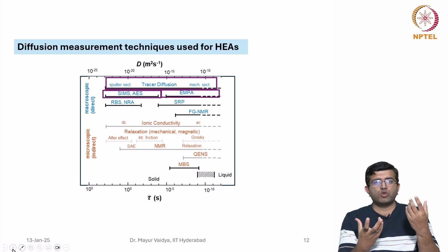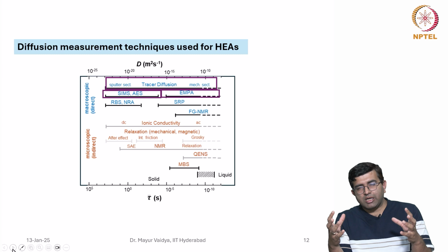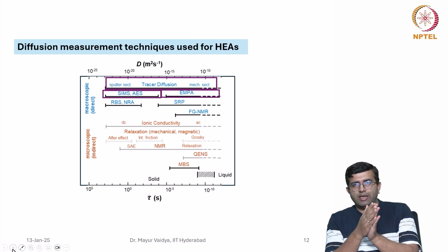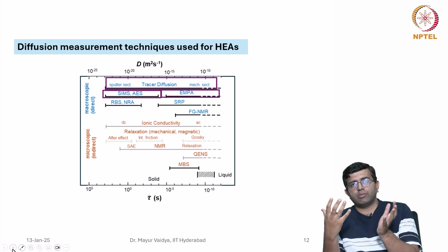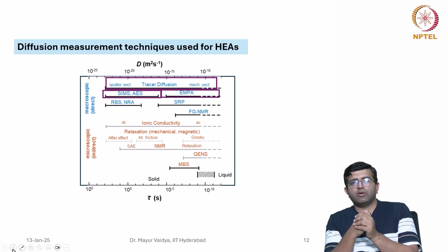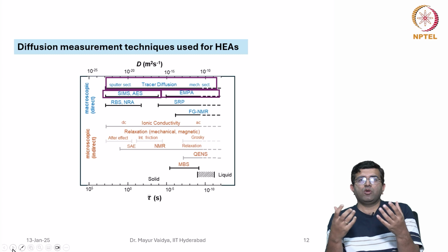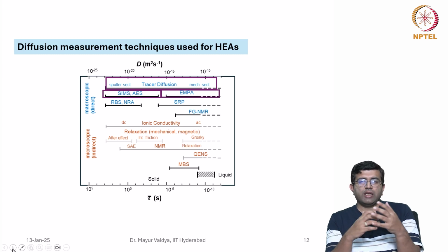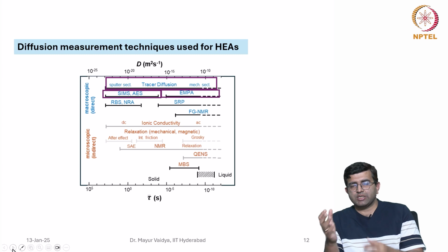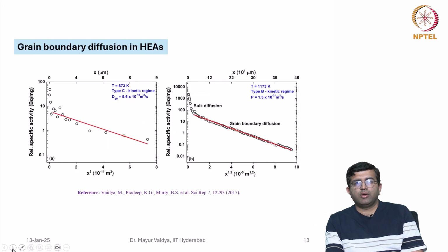So, design a diffusion couple such that although it is a multi-component alloy, you only get the gradient for 2 of the elements. If you do not use the pseudo binary way of doing it, then you make a multi-component diffusion couple, and it gives you an opportunity to understand the diffusional interactions as well. So, this is an example.